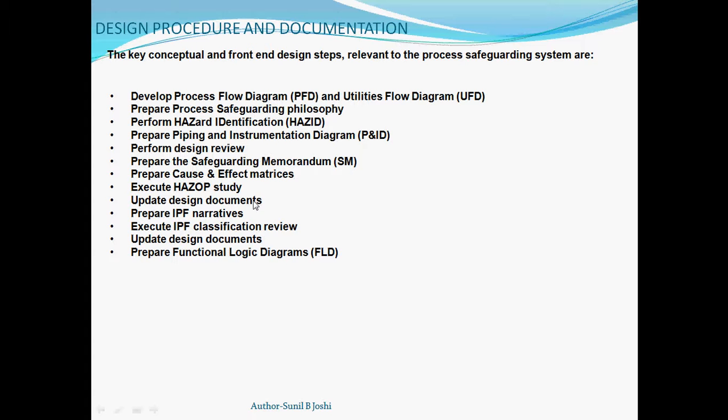Then update the design documents according to the studies. Prepare IPF narrative. So whatever the major IPF functions we have identified or designed as a part of the system, those are then applied for IPF classification review so that the SIL classification of those IPF functions is determined, and then update the design documents accordingly.